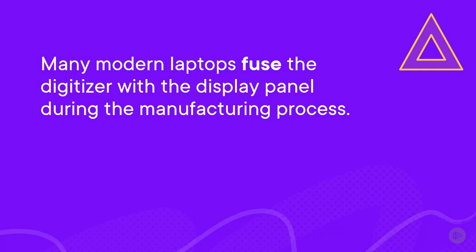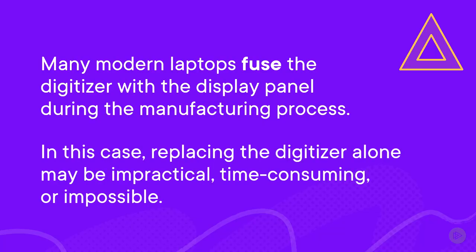Not all laptops use a discrete panel for the digitizer, and it's becoming more and more common for the digitizer to be laid onto the display panel during manufacturing. And if that's the case, you're probably going to have to replace the entire panel if a problem develops with the digitizer. It isn't usually practical to try to remove and replace the digitizer layer on its own, and the part may not even be separately available for order.